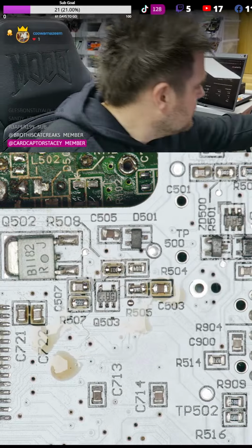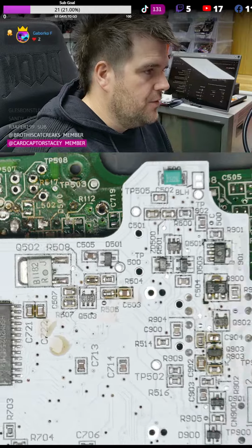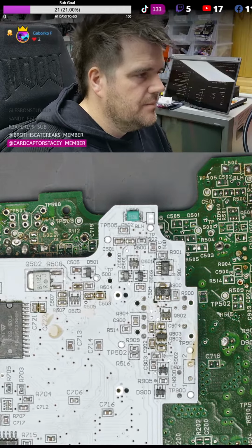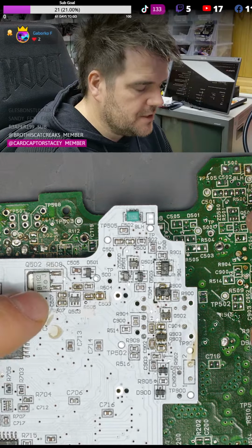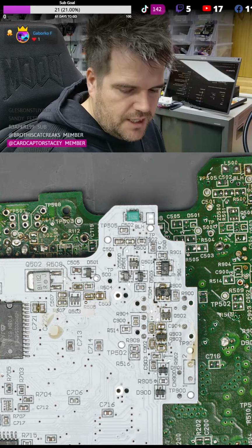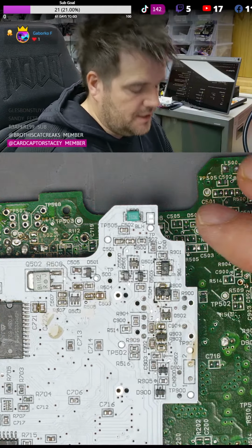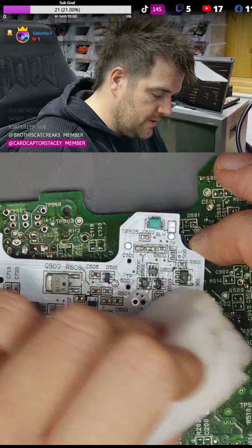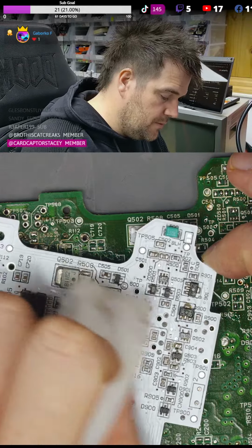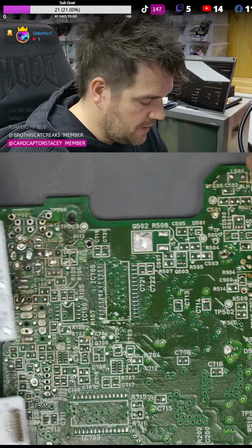And I suppose if we can't, for whatever reason, actually identify the few transistors that are left, they're on the power regulation circuit, so we could replace this with our own power regulation circuit if we wanted to offer like a pre-populated board with as many components. We could just literally replace this circuit design with our own switching 5-volt circuit. It wouldn't be too complicated.